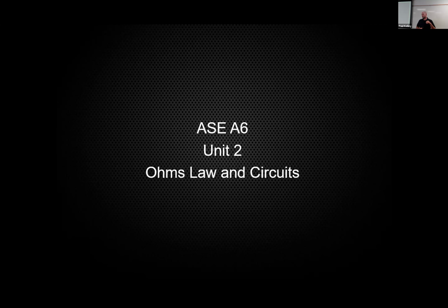If you have a 10 amp circuit and the math says it's now going to pull 12 amps, you know you can't do that. You can't just put the light bar in there and add a 15 amp fuse and leave the existing wiring that's good for 10 amps.